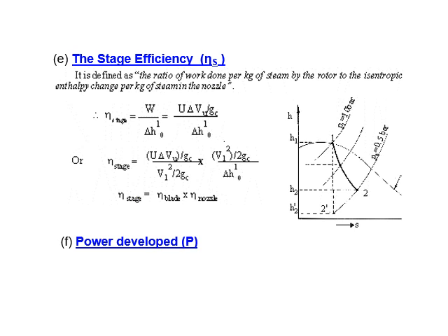Next, the expression for power developed. The power developed is the product of mass flow rate of steam into work done, that is m into the work done, which is given by U into Vu1 plus or minus Vu2. There is a change in tangential velocity, so power developed P is equal to m into U into delta Vu, and that power is obtained in watts. So these are some important expressions used in the steam turbine topic in order to solve the numericals.